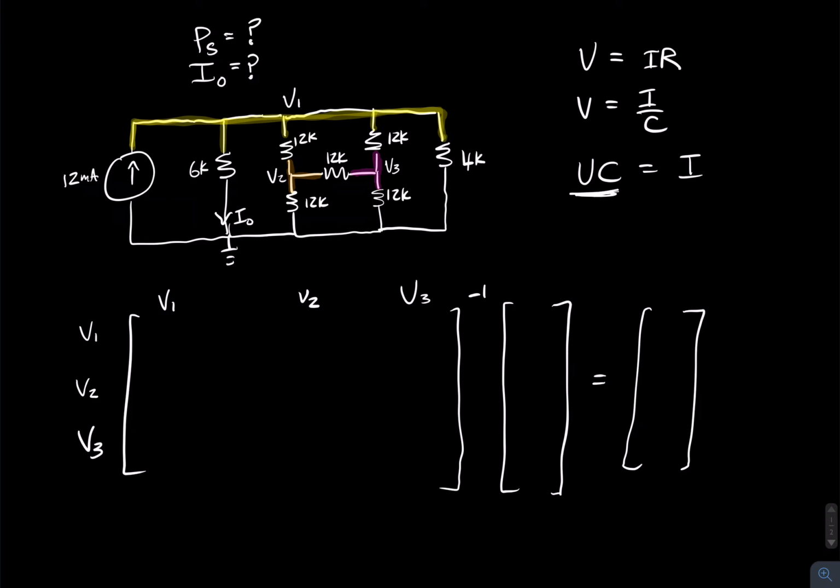So I is equal to VG instead of I being equal to V over R. Now it's exactly the same thing, so we're just going to convert all these resistors into units of Siemens. So just basically find the reciprocal. And if you didn't want to do this, you can just use the reciprocal of the resistance directly, but I like to remind myself that we're using the reciprocal here.